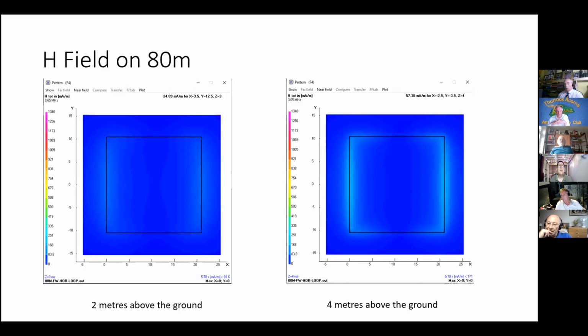Well, it will depend on the power. Something like a 23 centimeter long Yagi is probably a case where you're better just treating it in the far field. The Ofcom calculator uses a valid formula derived from Maxwell's equations that calculates the field strengths in the far field beyond the two wavelengths.